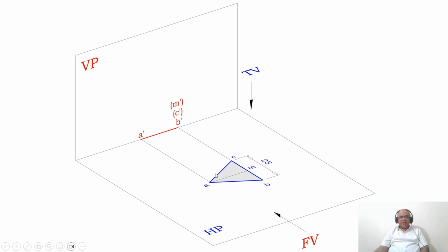So to do that, first we are going to take up the 3-dimensional sketch wherein you have a lamina. As I was telling, since one of its sides is resting on HP, obviously that side has to be perpendicular to VP. And the surface inclination is given with respect to HP, so initially the surface is made parallel to HP, that is 0 degrees with HP. Therefore you are getting a line. So what is the position of this equilateral triangular lamina with respect to both HP and VP?